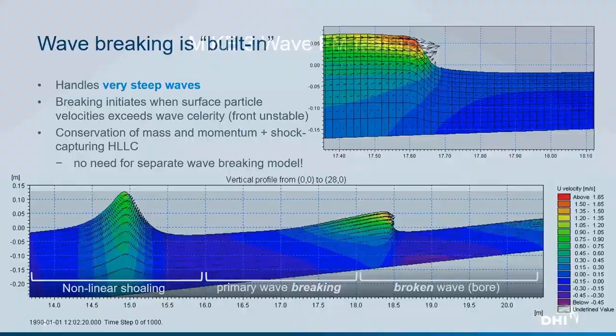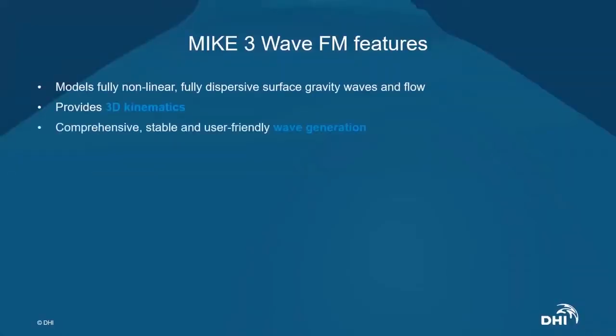Then some of these features, again, just to describe this, is that it is a fully nonlinear, fully dispersive surface gravity wave modeling suite. There are no limitations on the wave height, there are no limitations on the water depth, and the three-dimensional discretization allows for kinematics to be extracted underneath the waves.